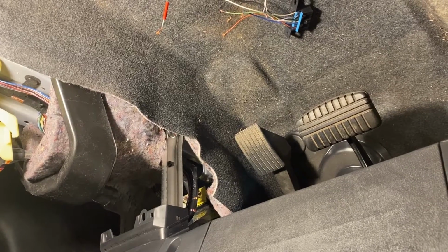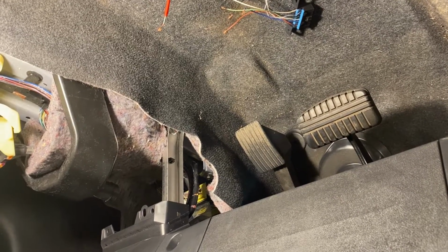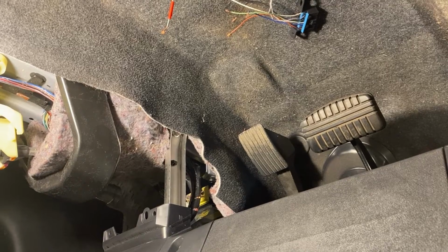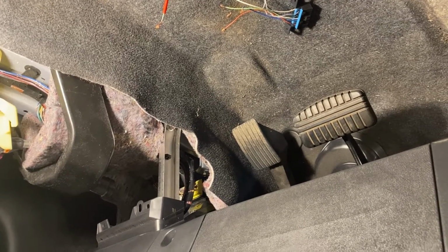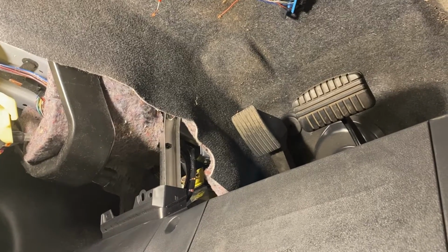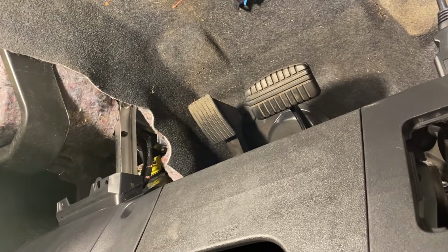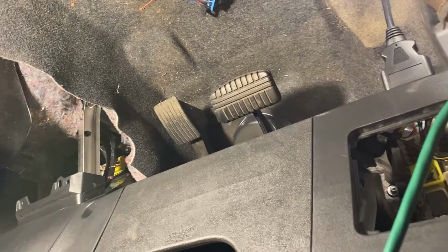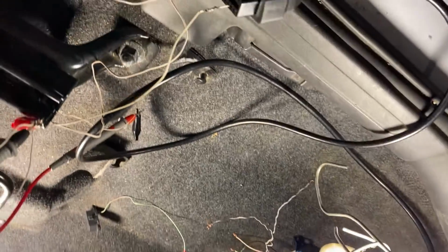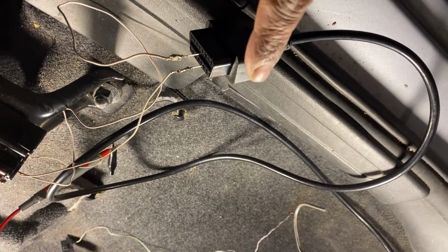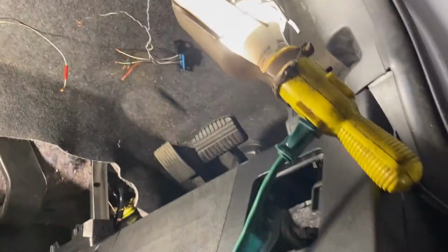If I come up with something else, I will make another little piece of video to continue with this. But at least we already know, before you measure the CAN bus for the car, you disconnect the battery and do like this. Never damage your board. I prefer to have an extension. Never play with a car board.